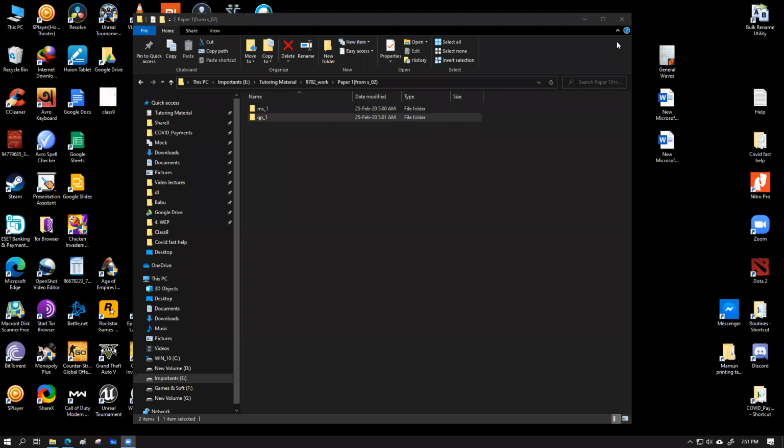And for the capacitor part, what we have seen in our last class is that while charging, the capacitor is going to slowly gain voltage, and given enough time, it will have the same voltage as the source, at which point the current in the circuit will decrease and eventually become zero. And also, capacitors store energy, not charge, because the total charge of a capacitor at any point of time is actually zero, considering both the plates together.